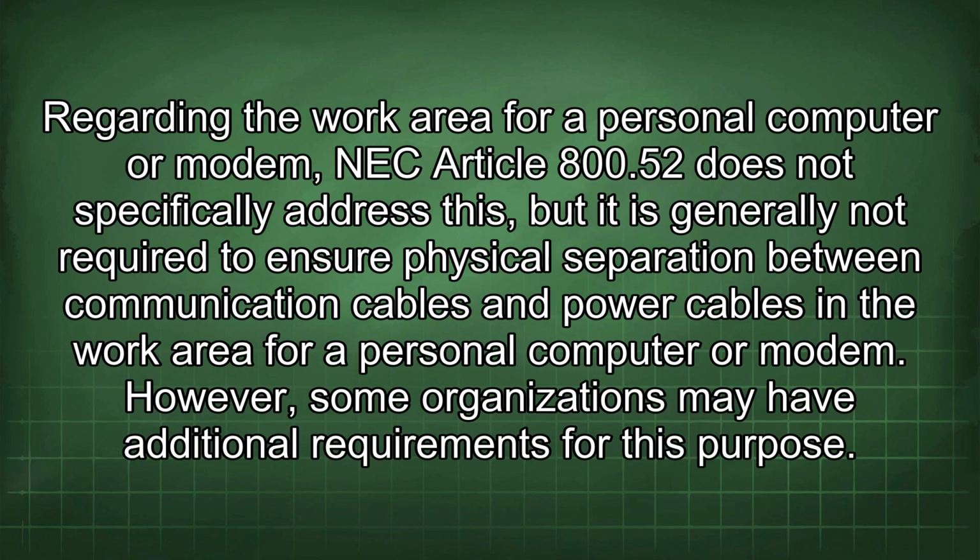Regarding the work area for a personal computer or modem, NEC Article 800.52 does not specifically address this, but it is generally not required to ensure physical separation between communication cables and power cables in the work area for a personal computer or modem. However, some organizations may have additional requirements for this purpose.